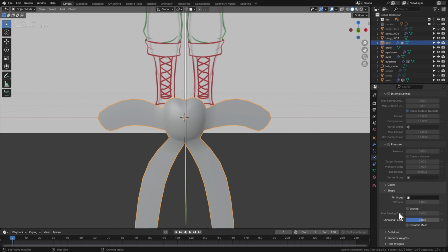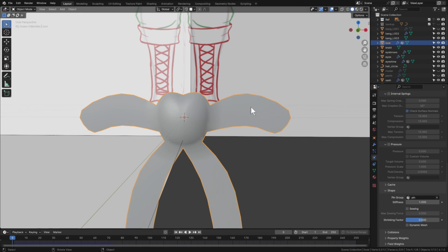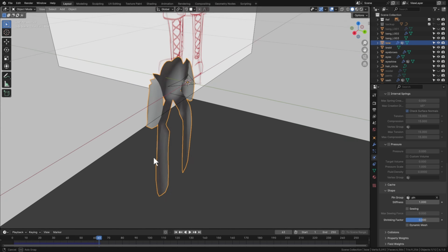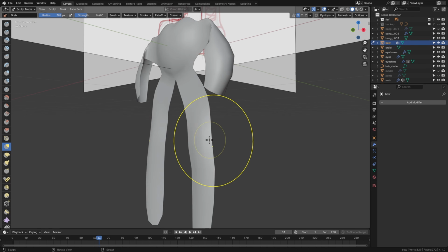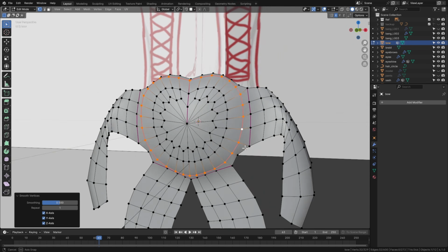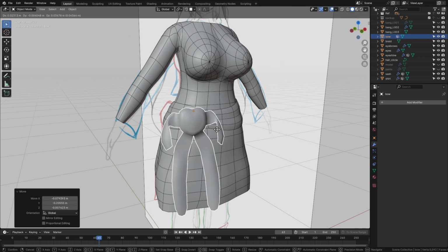Next, cloth physics can be used on the ribbon parts to give it folds. Do this much the same way, but this time making the pin group on the whole centerpiece. It's far from perfect, but it gets the job done. Convert the bow into a mesh to apply the modifiers, and smooth out the folds in sculpt mode to correct the creases in edit mode. Lastly, adjust the position of the bow as needed based on a reference of what feels right to you.